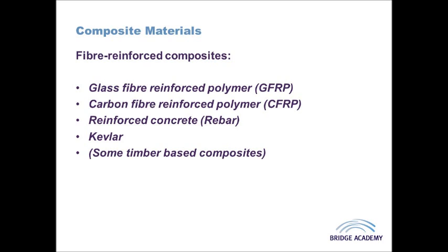Another example of a modern material fibre that is used in composite materials is Kevlar fibres. Now, this is a mixture of aromatic and aramid nylon-like molecules which are spun into fibres, and this is often used on things like bulletproof jackets, where we have very high strength to weight ratio, but also that toughness, that resistance to cutting, and that resistance to sort of flames, and resistance to many other things like this as well.